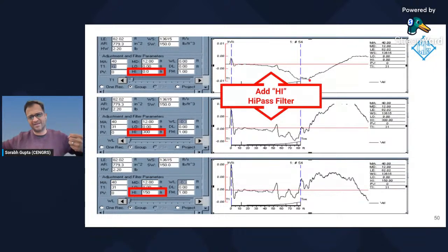The upward traveling wave carries a combination of the impedance of the surrounding soil as well as the pile concrete. So if the surrounding soil becomes dense at some depth, you get a hard layer, and your pile is going through a hard layer, then the soil resistance is also visible in this data.